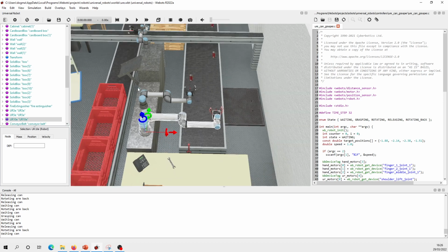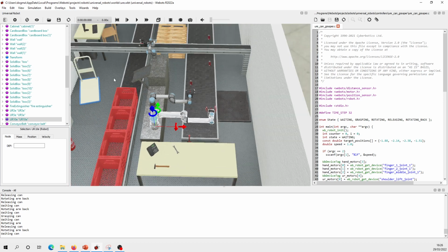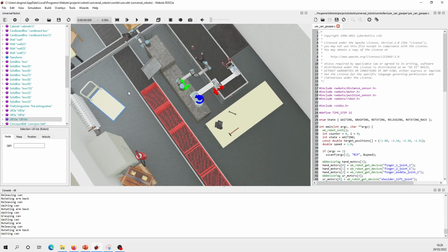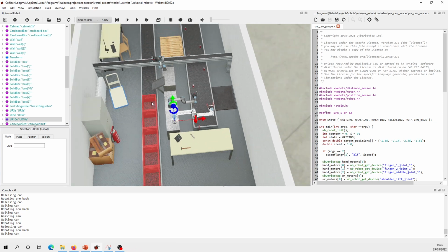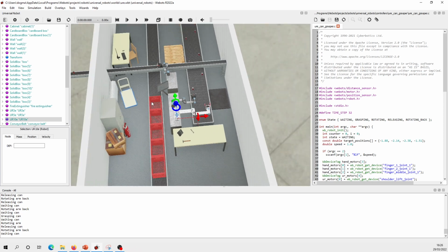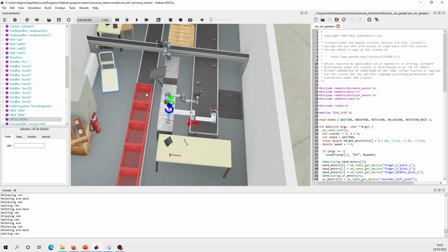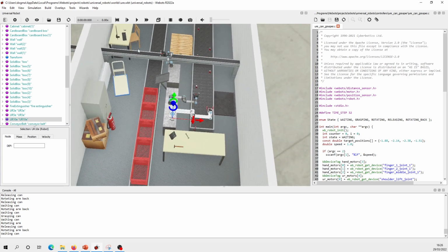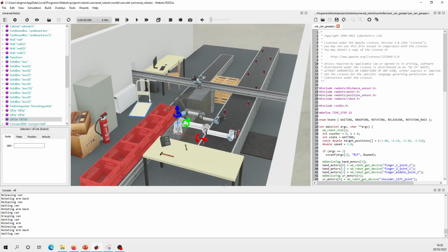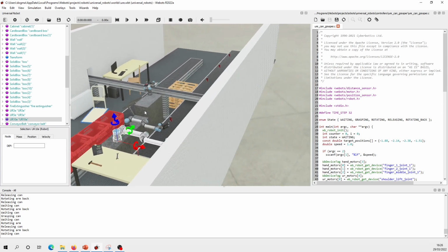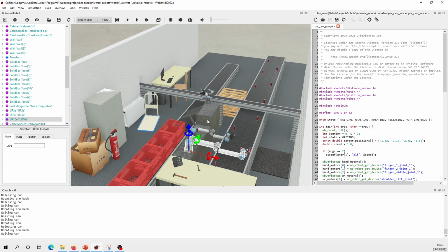So, just now remembering about the movement a bit, how to move around. Left click is going to enable me to rotate the 3D scene. With the wheel, I can zoom in and zoom out. I can also use the wheel to rotate and twist strange things, but I never want to do that. And with the right click, I can pan around. If you have played video games or other kinds of 3D software, this is just the way it